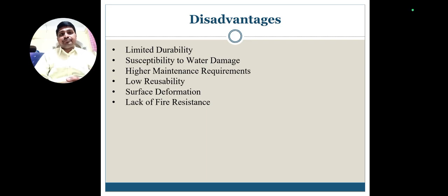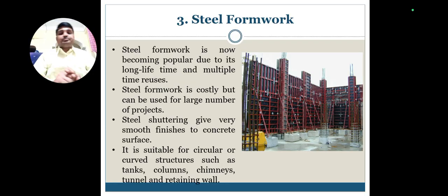Reusability is also low, because it is a timber material and may be destroyed after 6 or 7 uses, and surface deformation also occurs. The final one is the lack of fire resistance. Whenever a fire happens in the construction, it may not resist it.